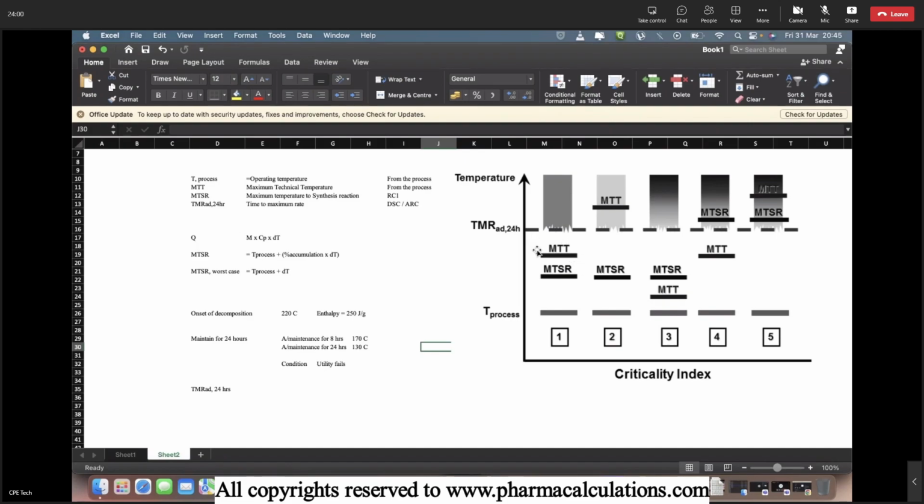And once the total solvent is evaporated, in such a case there is a possibility that the reaction temperature might reach the decomposition. So this is the decomposition line, and this is an undesired scenario. So we don't want to have decompositions in a reaction. Okay, so coming to class 1, basically your reaction mass doesn't have the potential to reach up to decomposition.